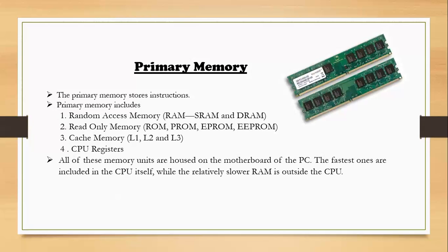It's a small circuitry which has to accommodate the arithmetic and logic unit, control unit, special purpose registers, general purpose registers. Space is required for these things. You cannot accommodate a big memory. That's why a small cache memory is included inside the processor chip.